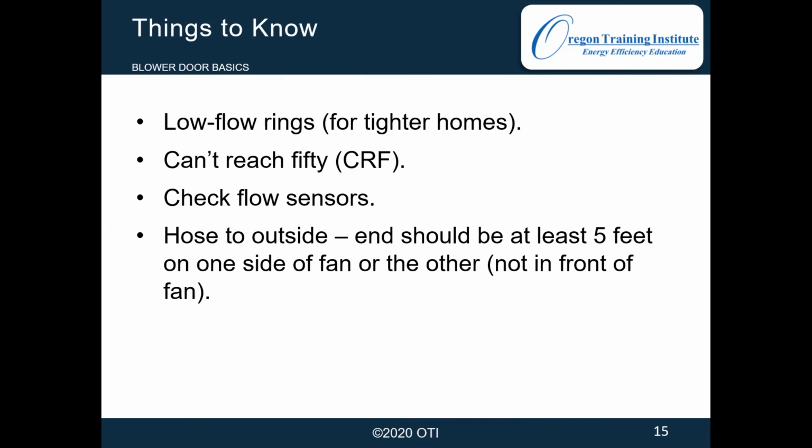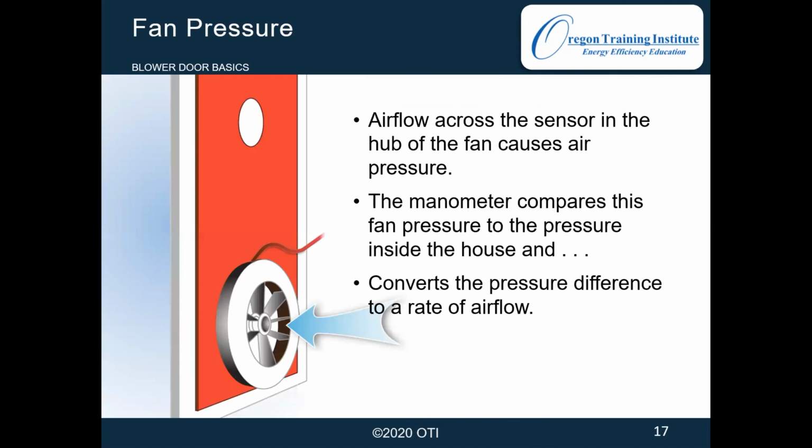So once we've got the house ready, we put up the blower door in the exterior door. And then we've got to set up the manometer. I've got lots of tips in here, some step-by-step on how to set this up. I'm going to pull it up on my real manometer here in a sec to walk you through it a little bit better.